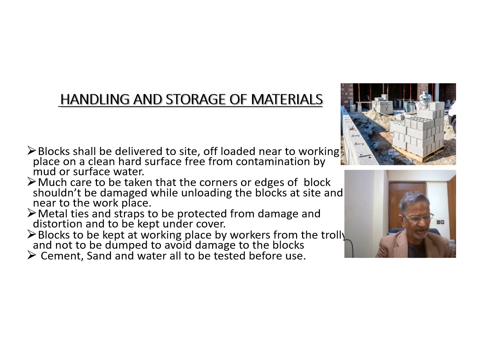Metal ties, as I told you earlier, are to be used between the columns and the masonry. These metal ties are embedded in RCC columns while you are doing the shuttering of the RCC columns. So these cares are to be taken while unloading the blocks or bringing the blocks from the yard to the site.